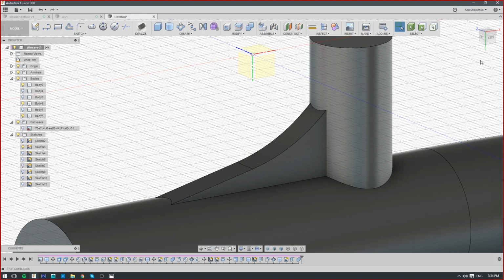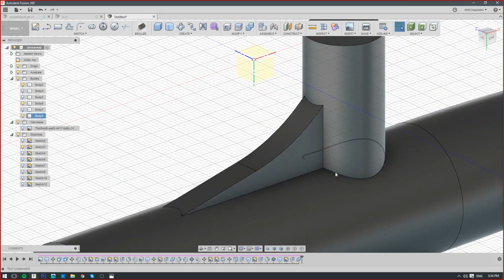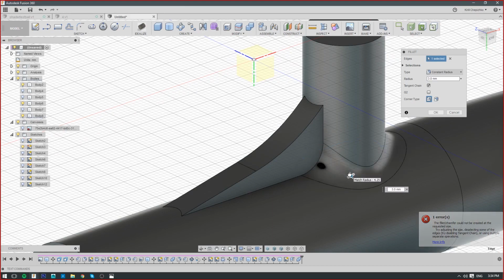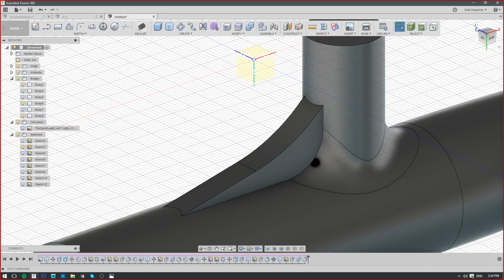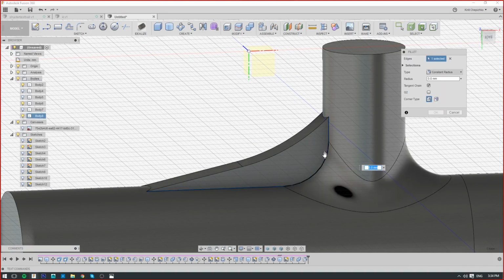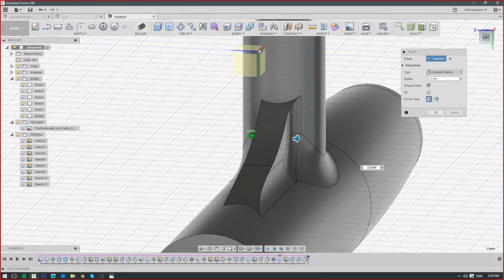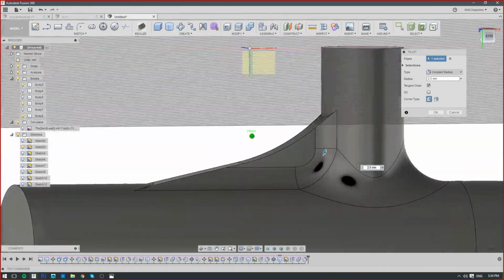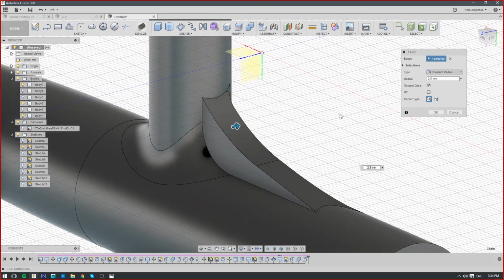In this case, it doesn't matter. I combined it. What matters is the order of fillets sometimes, because if I do this fillet first, obviously it goes higher, and then the second one will be slightly different. So it changes the shape. Yeah, I see. And this, for example, shape is a lot more organic than what I had before.